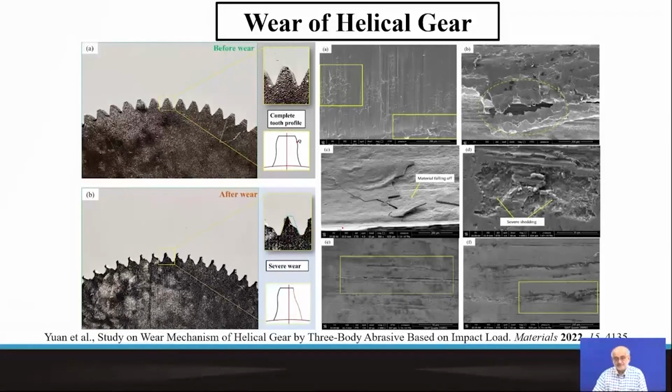Most of these nitrides are interstitial compounds, usually line compounds, so they are very hard, with extremely high hardness and complex crystal structures. They also are very brittle. And in the process, we accrue a lot of benefits in terms of wear resistance, hardness, chemical inertness or corrosion resistance, and even at times residual compressive stress on the surface.